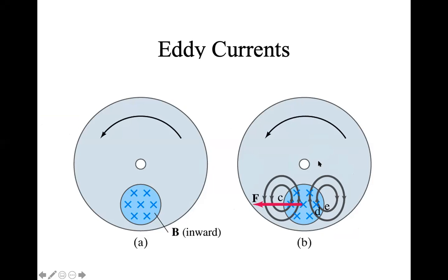And we're talking about these eddy currents. The point, I guess, is as a piece of metal right here that isn't seeing a magnetic field goes to a region where there is a magnetic field, you might think of this like a big horseshoe magnet with two poles. You'll see that in a video here in a second. That could be what's creating this magnetic field right here. As the piece of metal goes from no magnetic field to a magnetic field, an electric field is actually generated, which causes an electromotive force, which makes currents swirl around. And then that current interacts with the magnetic field to give you what I would call a retarding, a slowing down force. And you'll see that very graphically here in a second, okay?